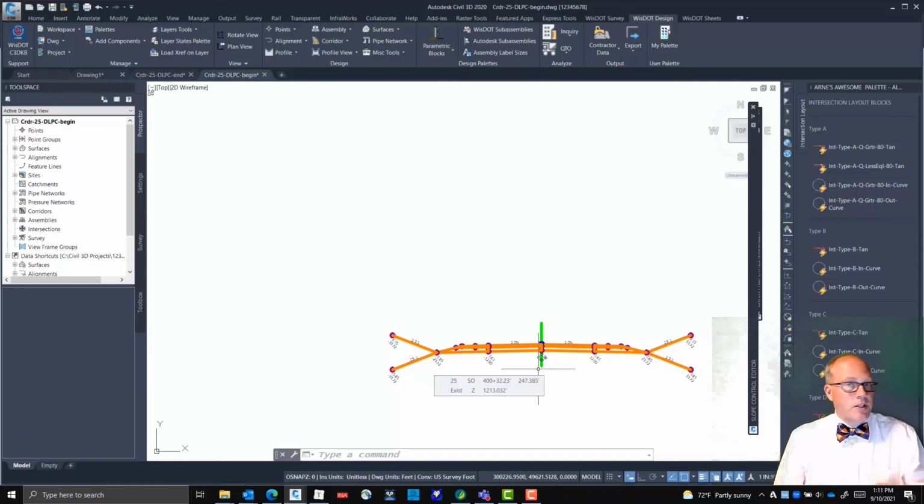the place where this particular sub doesn't work is in urban, because you've got outside in design, and your variability is still there, but you're talking about maybe one link past a sidewalk, or maybe it's truly concrete to concrete. We've still got profile controls for lane and sidewalk subs there. So you can take those same concepts, because even in urban, you've got existing ground that you've got to hit. So that is what I had to show you today.